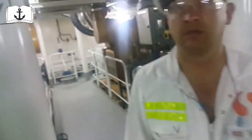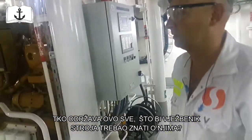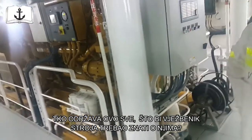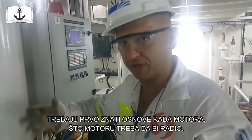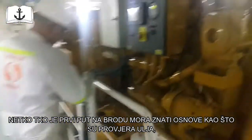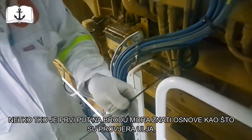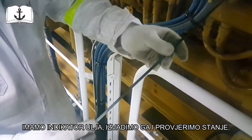So, who does the maintenance of this? If you are an engine cadet, you came on board, what would you have to know about these little things? I think they should start from the beginning, so the construction of the engine, what the engine needs to run. And then I think the guy who has never been on board should learn these basics. So you're checking the lube oil, here is the stick. You should have a certain amount of oil. It's written on the stick also.